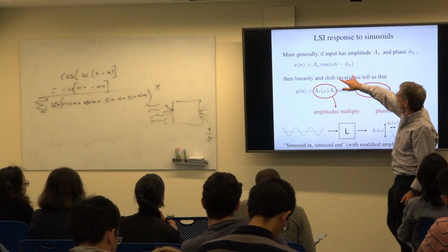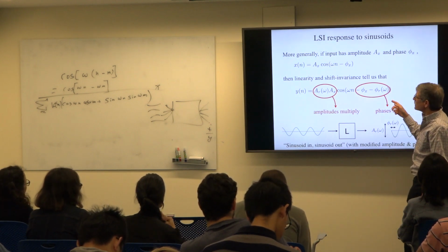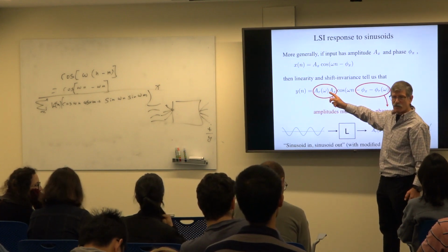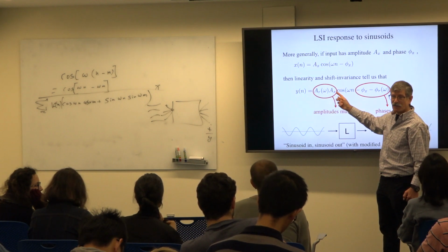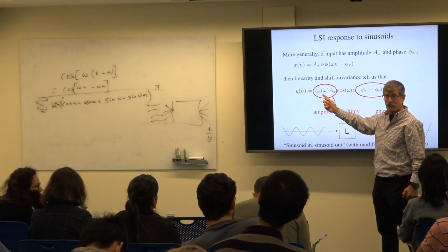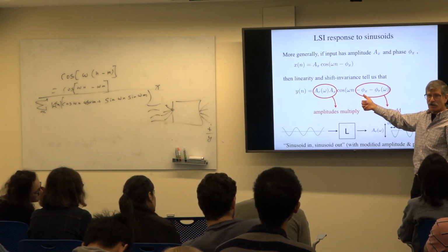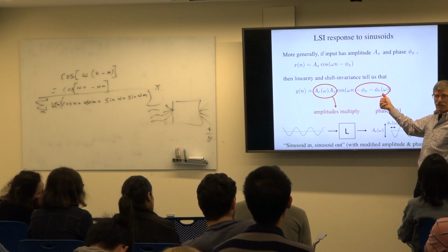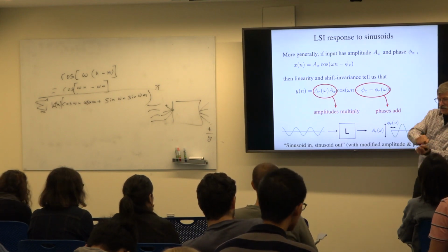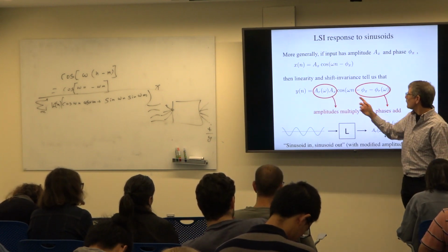But just let's point out when we put in this general cosine wave. This is the formula I had before, but let's see what the formula does. It means here's the amplitude I put in. It gets amplified further by what the system does at that frequency. So the amplitude of the input times the amount the system amplifies at that frequency, those two get multiplied. Phase shifts, on the other hand, get added. We were phase shifting by x in the input, and we were phase shifted further because the system delayed it by phi r. So phase shifts are shifts, and so if you do 2 shifts, the shifts add. Stretches multiply. So thought about it in the polar coordinates way, these guys multiply, these guys add.